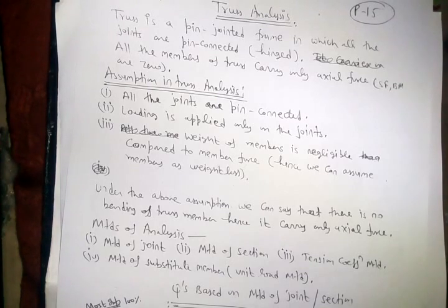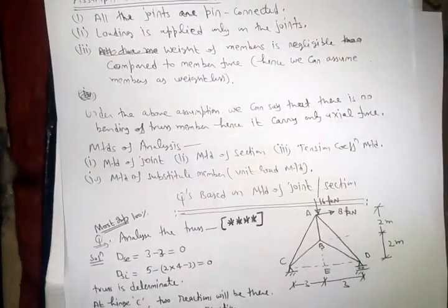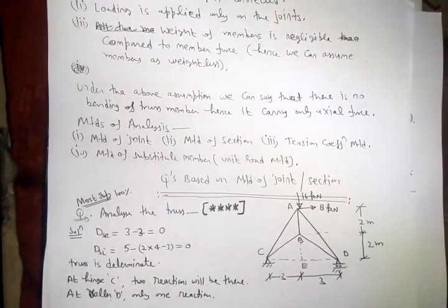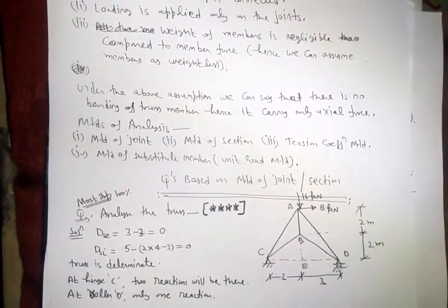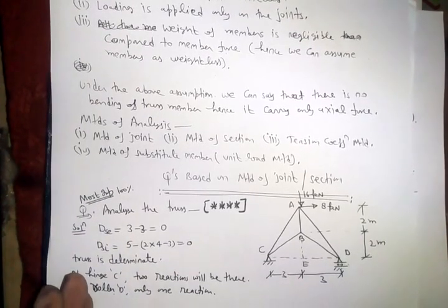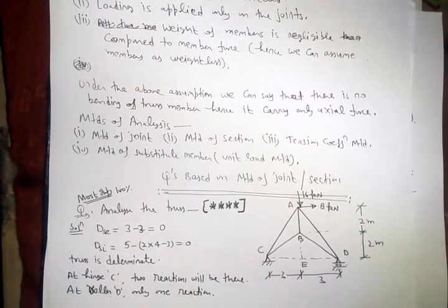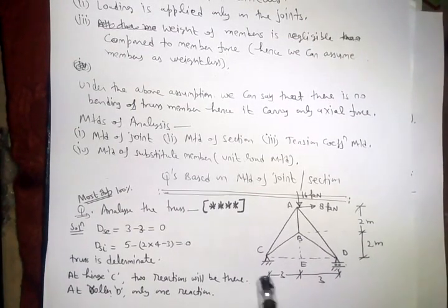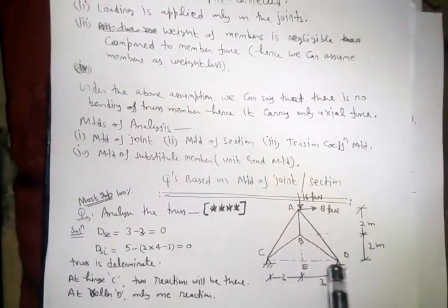We will see together. So question 1, this question is frequent in UPTU. The question was asked 2 or 3 times in UPTU, so I have written it as most important. So let us see. Dear friends, first of all, while analyzing the truss, we will calculate DSE and DSI. DSE: the reactions are, this is a hinge, this is a roller, so 2 plus 1, 3.